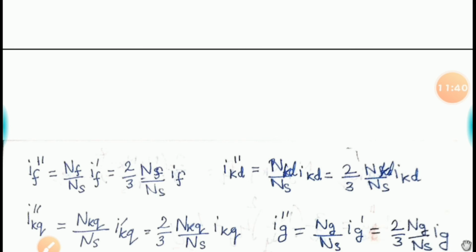But if we want to express all these terms, this IQ, ID, we now have a symmetric matrix, but can we do something to refer all the things to the stator, bringing them back to the stator reference frame, but just the magnitude? We are interested in magnitude.